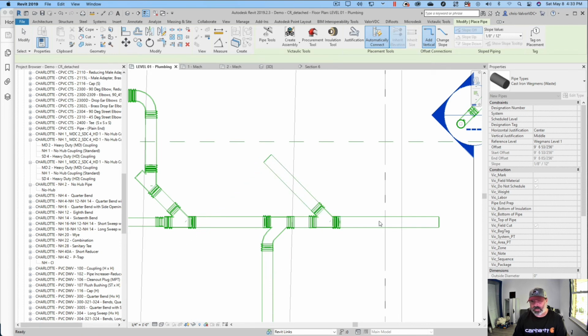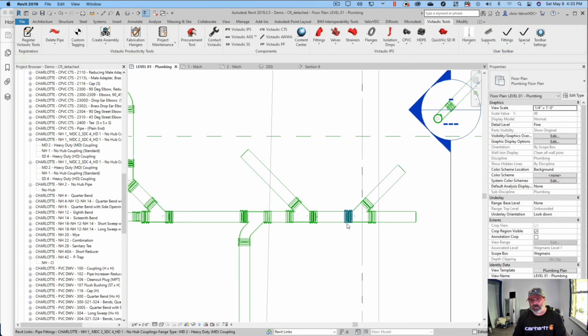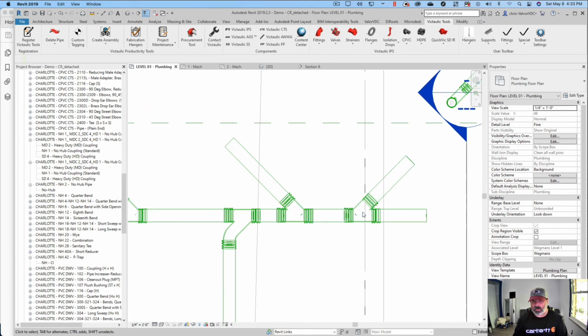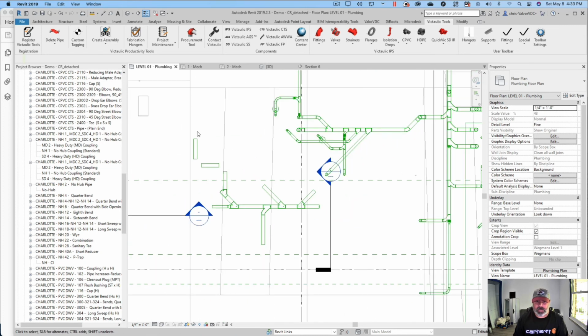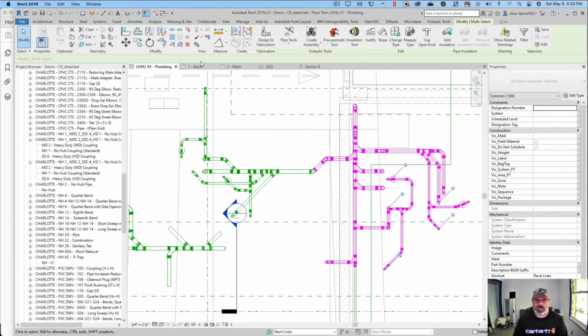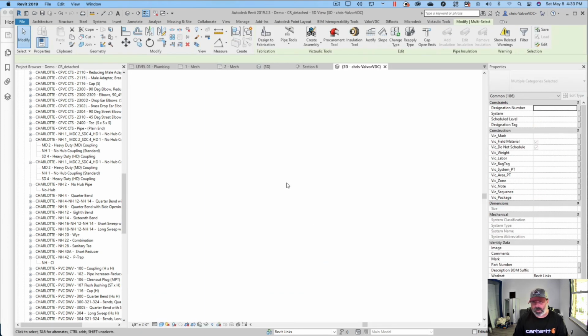And if you're drawing a vent system, click, inherit elevation, 45. And it'll draw a Y. And if you're trying to build a model that's fabricatable, these dimensions are exactly the same. So what it does is it takes the outlet and it just moves it from one end to the other. I think it's 2 inches from the bottom on a 4-inch. So it just flexes back and forth. And if you want to see what this looks like, let's get a pretty good line here of these bad boys. And that's what they all look like when they're run.